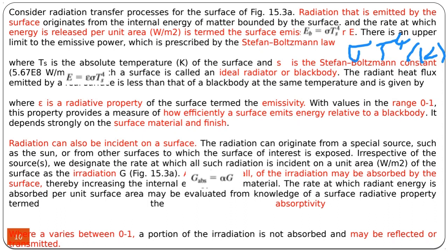On the surface, its maximum is 1,000. And because of the conversion efficiency of solar panels, which is recently 20%, it used to be much less than this. Maybe in the future it will be greater than that, but for the time being, you can get 200 watts per square meter of solar panel.